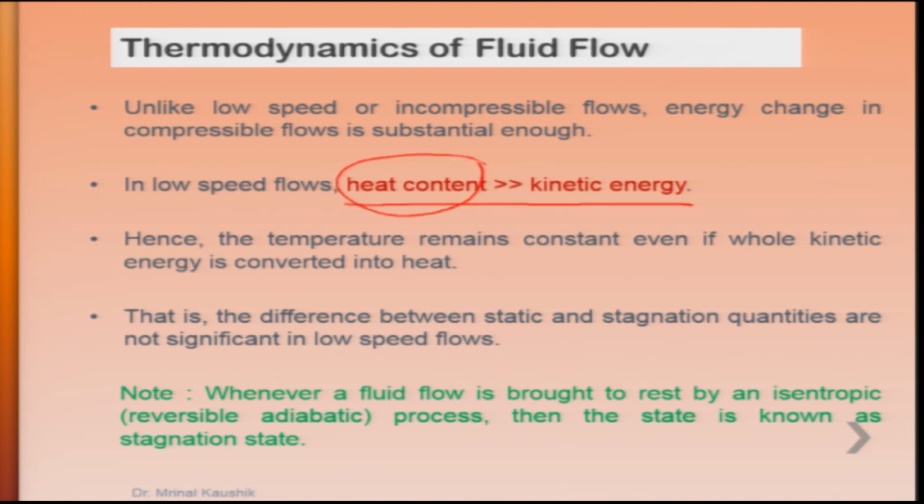That is due to its larger heat capacity. Even though the whole kinetic energy is converted into heat, the difference between static and stagnation temperature, or static and stagnation properties, is not much; it is very small. So, we do not define static and stagnation properties differently in an incompressible flow, while in compressible flow